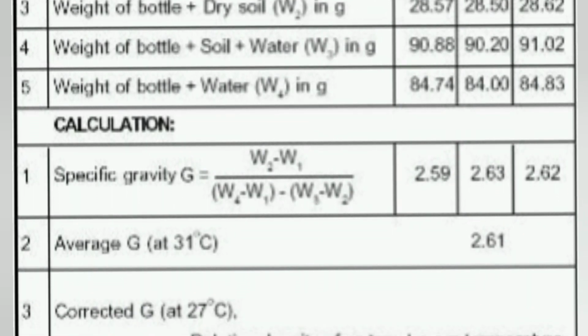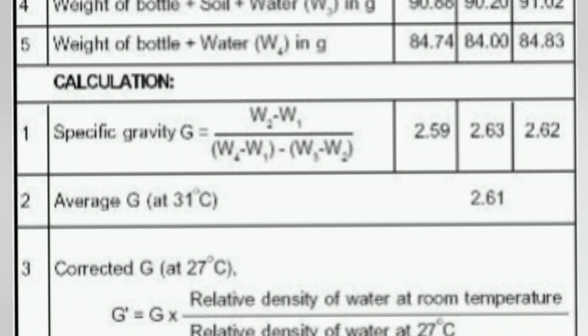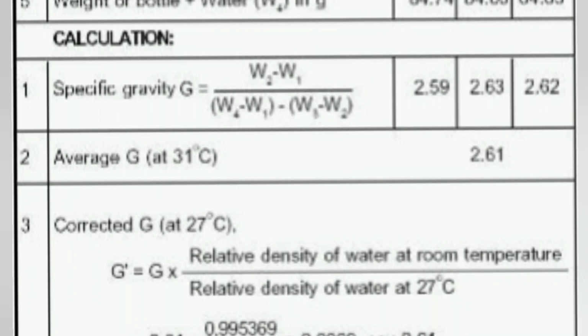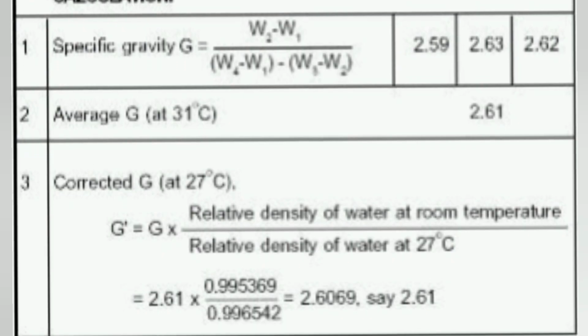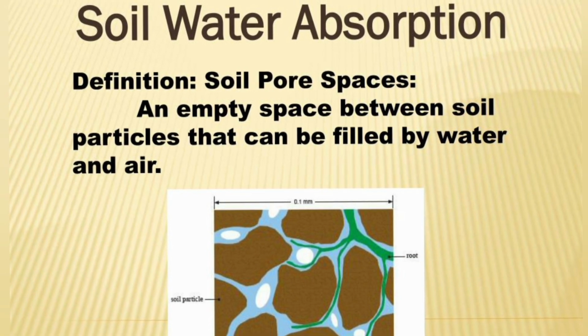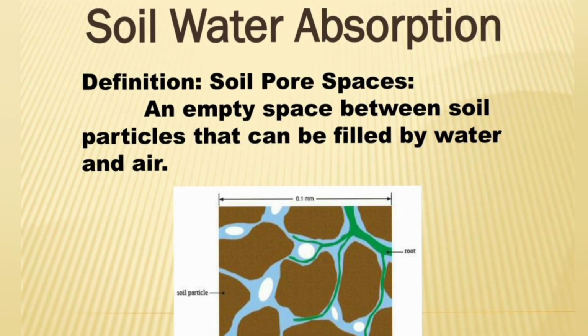Water absorption measures the amount of water the aggregate can absorb into its pores. This is crucial for mix design because if the sand is highly absorptive, it will steal water from the mix, reducing workability and affecting the vital water-cement ratio.